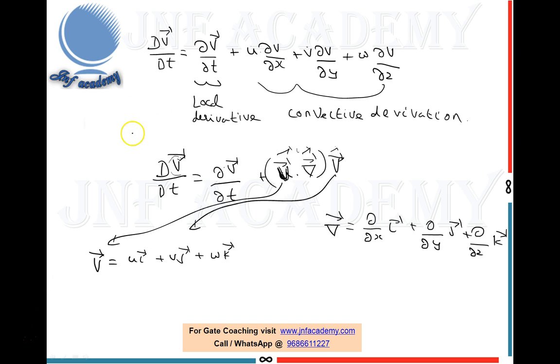So now I hope you understand what is the Eulerian approach, what is the Lagrangian approach, and how we have got the Lagrangian derivative here, right? So now if you expand this in vector form, because this will have a vector, this will also have a vector, you will get, what is dV by dt? It is nothing but acceleration, right? The rate of change of velocity is nothing but acceleration. If you want to know the acceleration of the fluid particle, then you will get three direction accelerations.